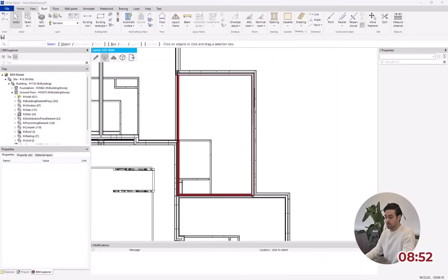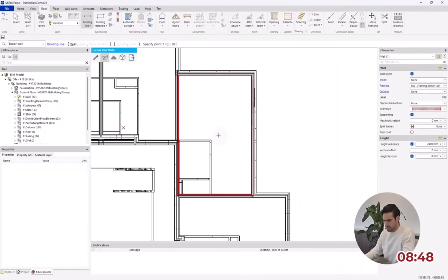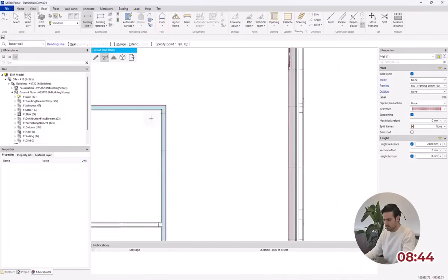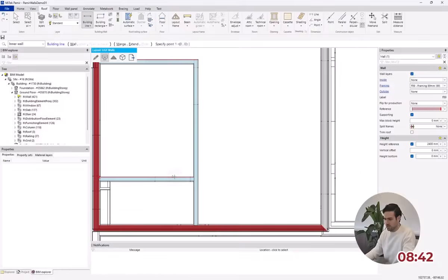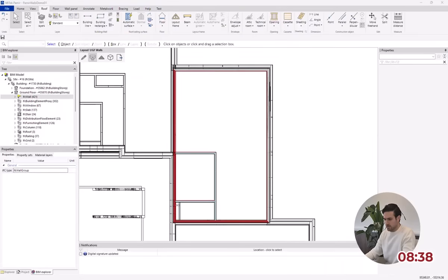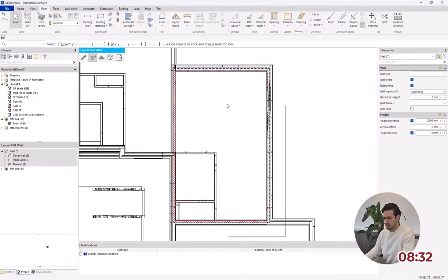So now I have the outer walls in, I can now add the internal walls. The extend feature really speeds up this process. So now that all the ground floor walls are in place, I can copy these up to the first floor and easily adjust them to suit.